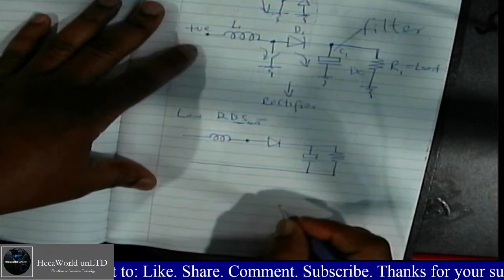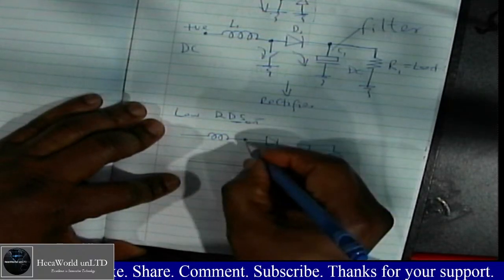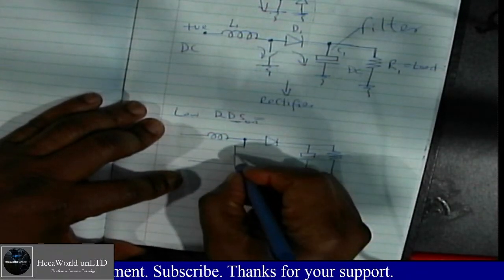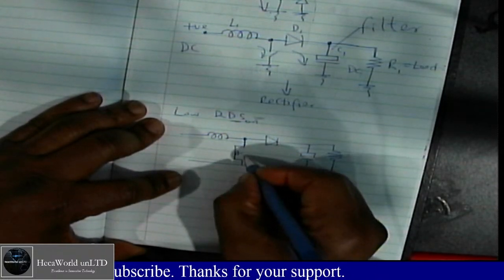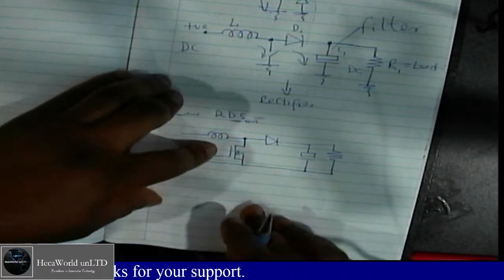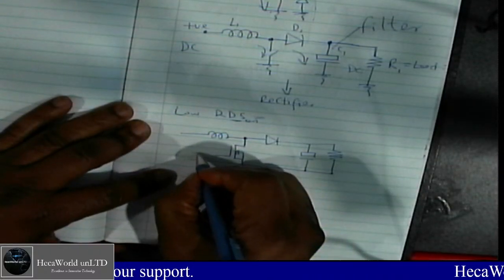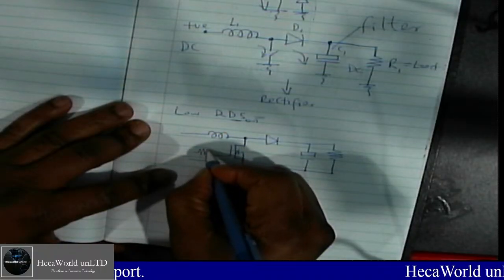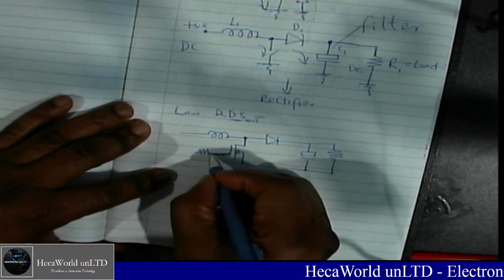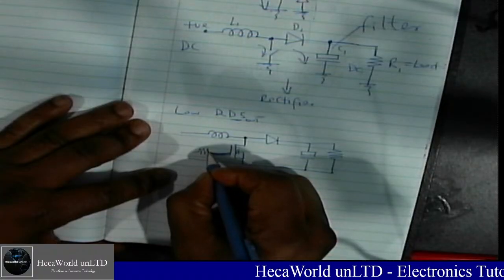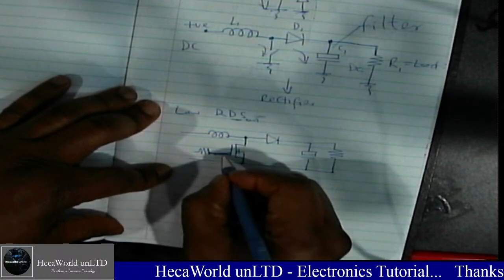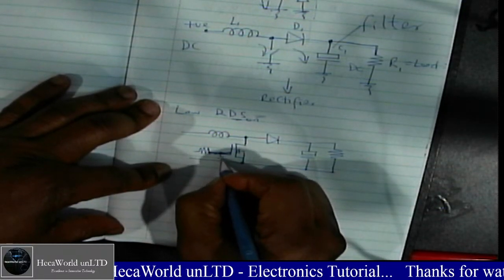So here we're gonna use a MOSFET. You're just gonna connect it like this, and you're going to use an N channel MOSFET. All right, so that's the switch. And then the pulse, so we're going to put two resistors here. Okay, I didn't draw this gate properly, but you get the point. And then I'm going to use another resistor to ground here.